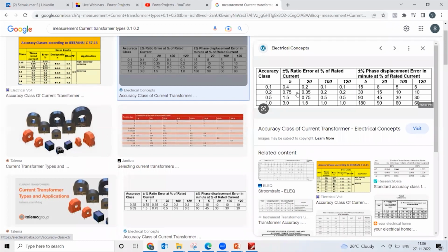You will be having very high ratio CTs to cater to the full load, but during such durations you will draw a very small quantum of power and you will not have accuracy from CTs, and sometimes the CTs may not even drive the meters.